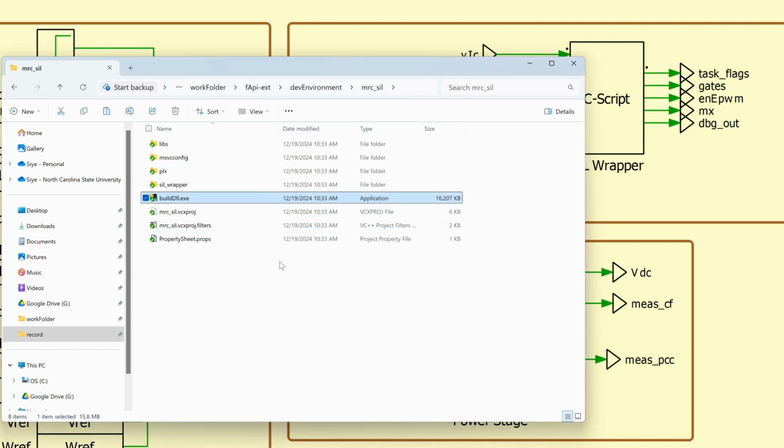There are two parts to prepare for the DLL build. First of all, Visual Studio needs to be installed on the user's computer. And second, we will make sure that the MS Build path is added to the path environment variable. What do I mean by the second step?